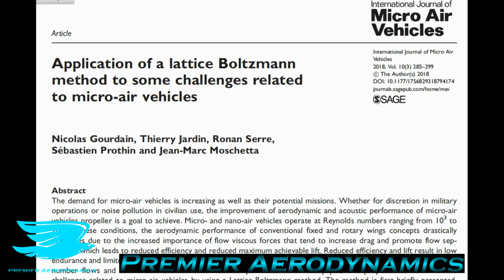So let's start off with our basic setup again, where we have our simulation and we are running it on one core, and it takes 20 hours. Then if you run it on 2 cores, it might only take 10 hours and a couple minutes. And then you run it on 4 cores, it might take 5 hours and a few minutes. And then you run it on 1,000 cores, and it reduces it by the equivalent of 99.9% or 99.8%. So it scales very linearly, which means that we are no longer hampered by this limitation in cores that we can use, and that is very beneficial. So that's where the Lattice Boltzmann strength comes into it, and it's a major strength.